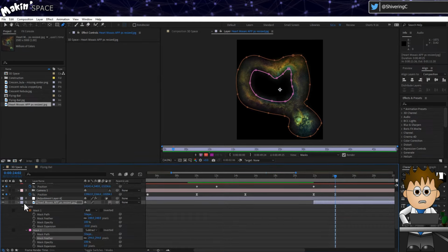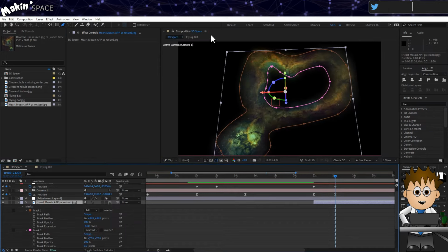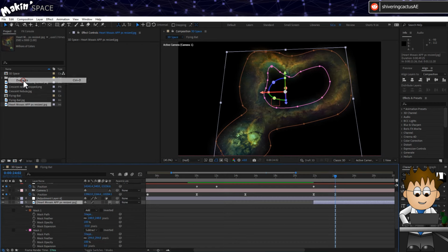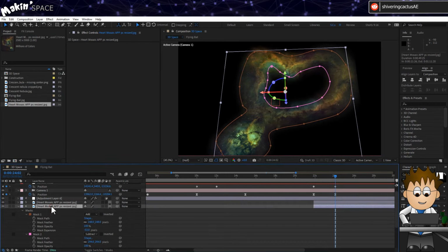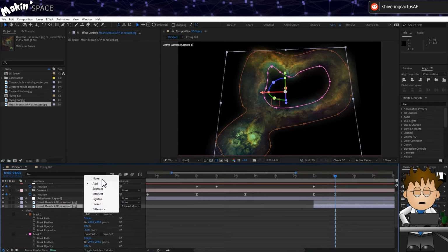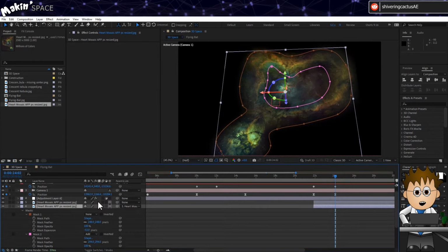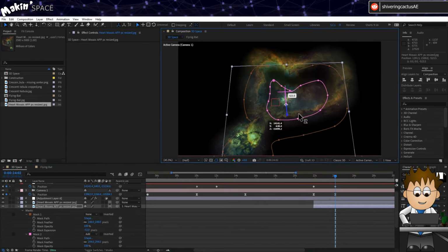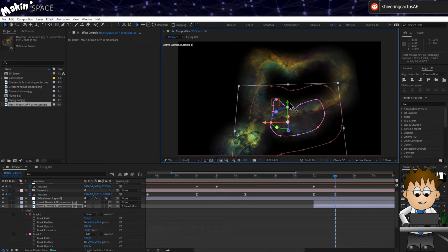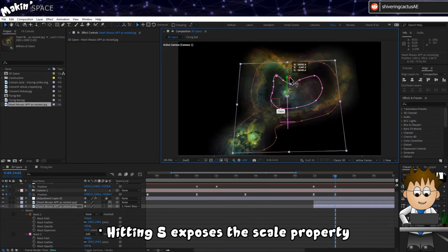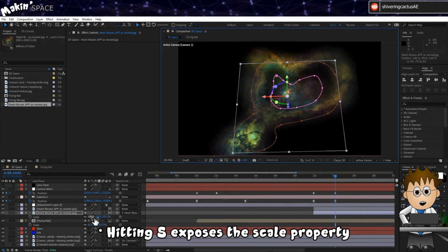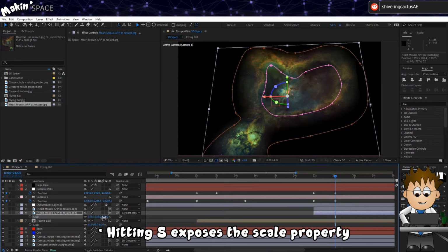Now, click close on the preview window, then with the layer selected, go to Edit, Duplicate. On the lower layer, make it a child of the upper one, and in masks, set mask 1 to none, so it has no effect, and set mask 2 to add. Push this layer back in Z space. And then scale it up so it matches where it was, roughly.